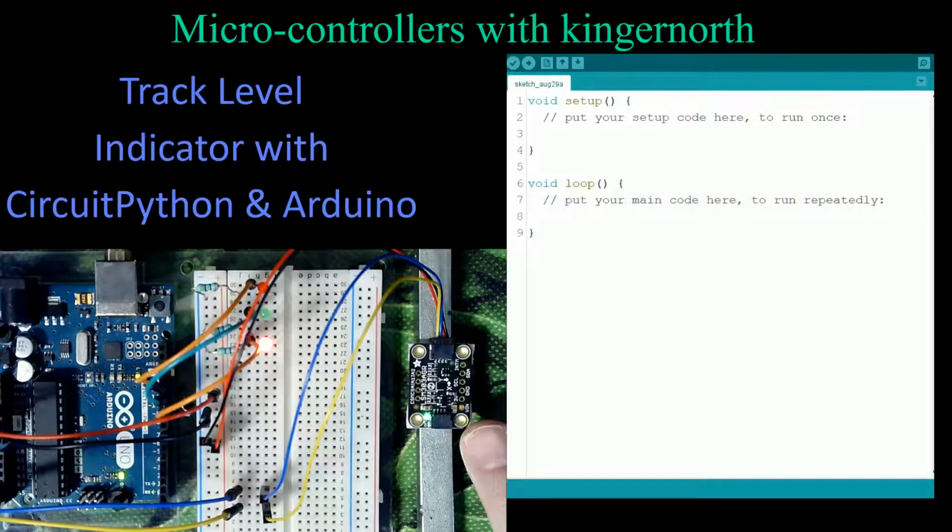It's pretty sensitive, and you should calibrate this, or you just adjust your program accordingly, because every time you get one of these boards, don't forget that little sensor in the center of that board there is actually soldered in place. And that means that it could be slightly higher on one side than it is on the other because of the thickness of the solder when they solder it on. And if that happens, even the smallest amount off level is going to throw this thing so it's not level when you start. So you calibrate it on a known level. You put it on a level and then you can calibrate it.